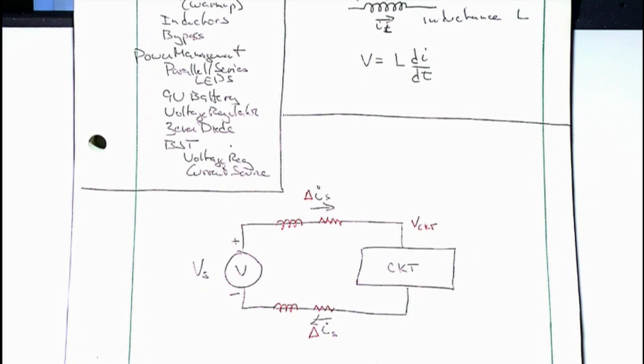If you've got a circuit where 0 to 10 volts is temperature, and you want to be able to measure temperature to a millidegree, well, a millidegree is now 10 millivolts. And if the current changes enough to cause a 10 millivolt change, you've now lost your error margin. So how can we fix that? We want this voltage to be stable, but we've got to connect it up with wires. Wires have inductance, wires have resistance. What element do we know that resists changes in voltage?